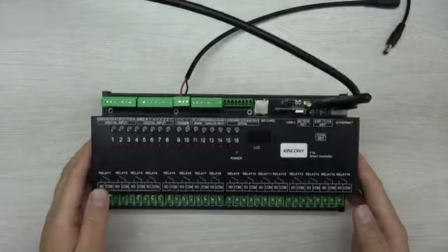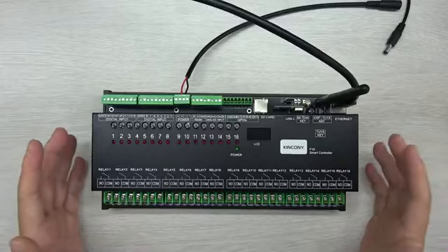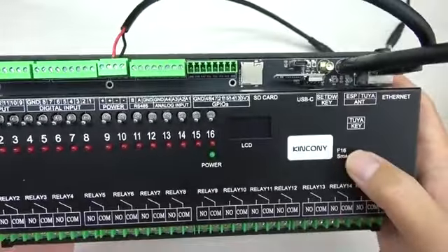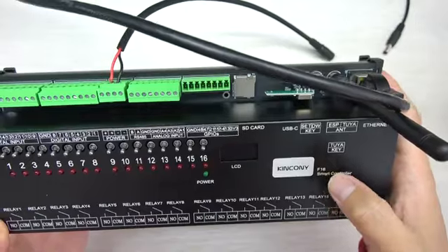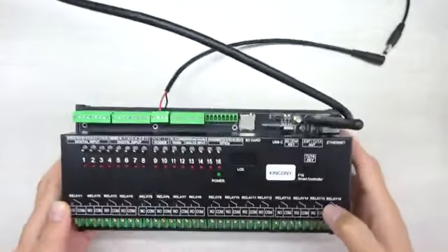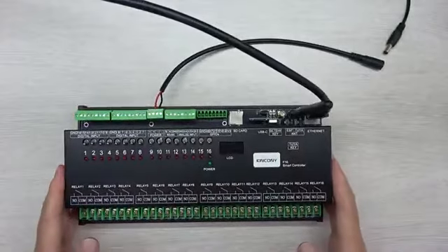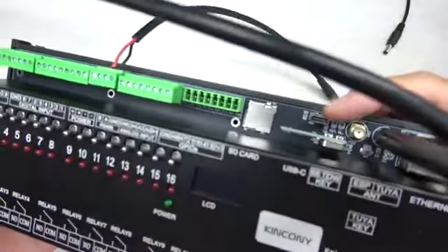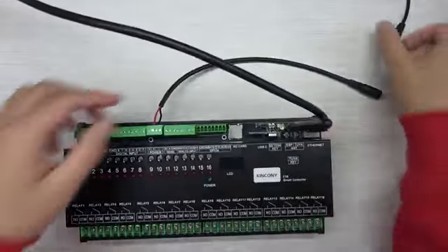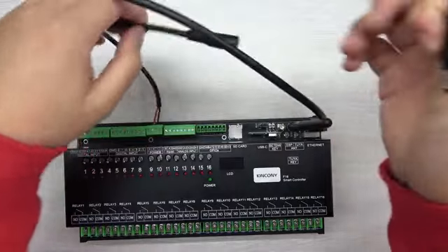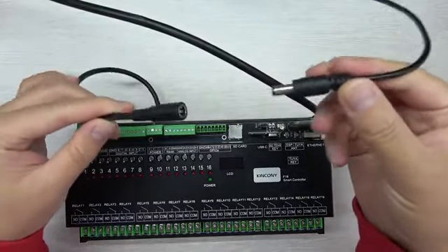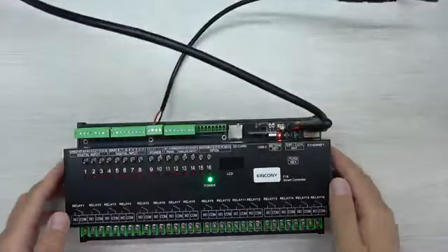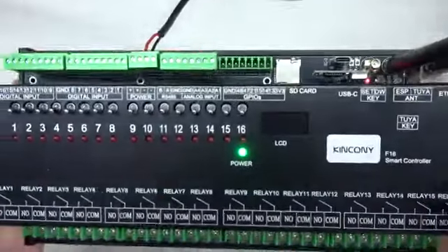Let's look at it. If you have used the KinCony platform, choose an F16. So you can see this is F16, and you can also choose other product modules. I just take an example. After you download the KCS v3 firmware by this USB-C cable here, we can power off the controller. This controller has DC 12 or 24 volt, two different types. You can see power on, and wait for a moment.